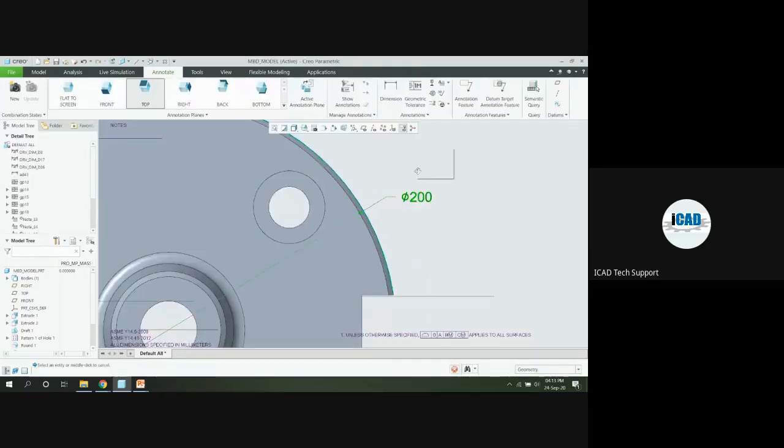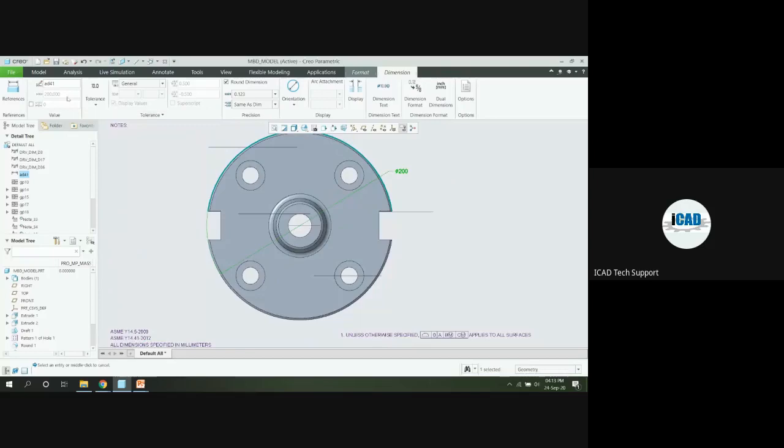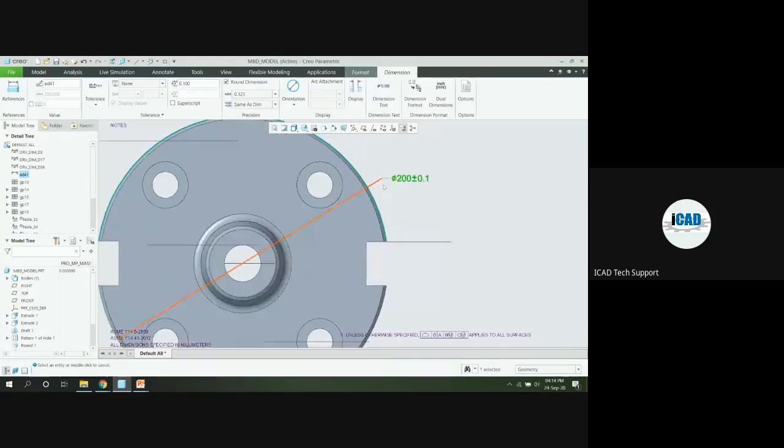So for that, you can see I'm adding the shaft basis, hole basis tolerances. I'm setting a normal tolerance, for the symmetric tolerance value, and here a 0.1 tolerance, plus minus 0.1 tolerance from here.